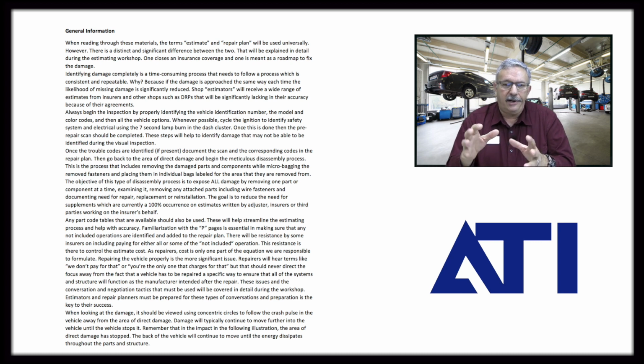That 7-second burn looks at certain systems, but when I look at the scan process, it looks at the entirety of the system. It looks at the control unit and what the control unit has found wrong with all the systems within the vehicle.